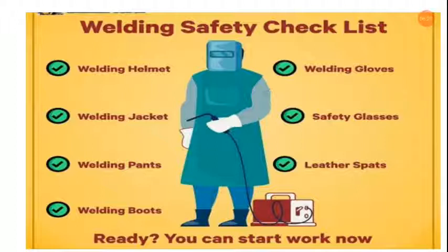Don't rest your body, arms, or legs on the workpiece, especially if clothing is wet or bare skin is exposed. Under such very poor welding conditions, you have to follow these rules or use a semi-automatic constant voltage welder with a cold electrode, or a stick welder equipped with a device to reduce voltage at the electrode when no welding is being performed.